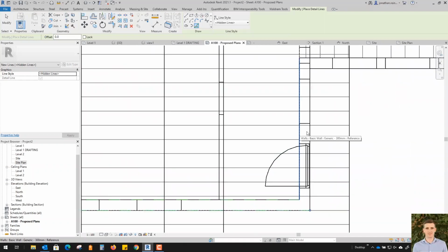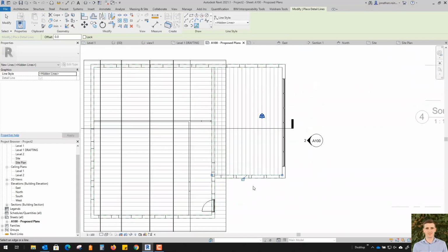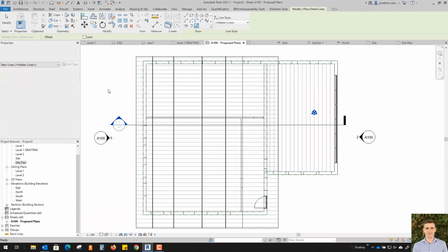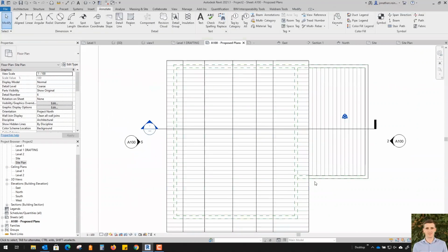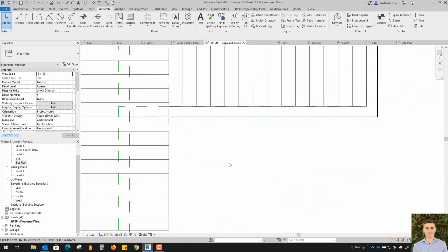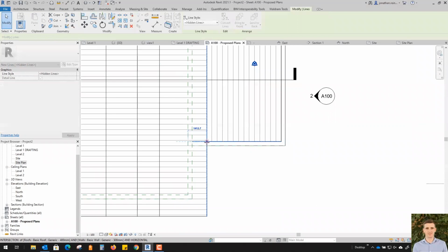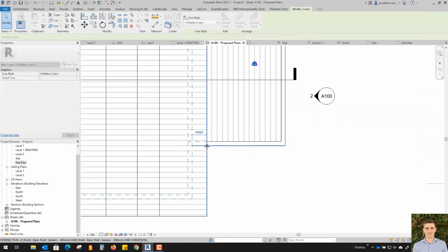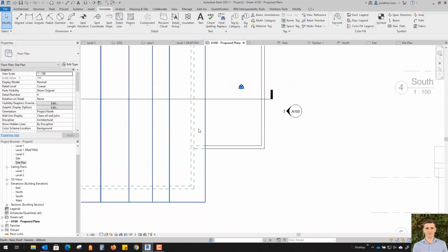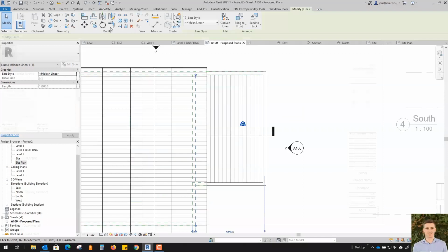Once we go back into the hidden lines view, all you will see is the roof outline, and then the outline of the internal floor plan. Some designers like to have their drawings represented in this way, and this is how you might do it, by using that annotation detail line. These only exist in this particular 2D view. They don't change anything within your 3D environment at all.